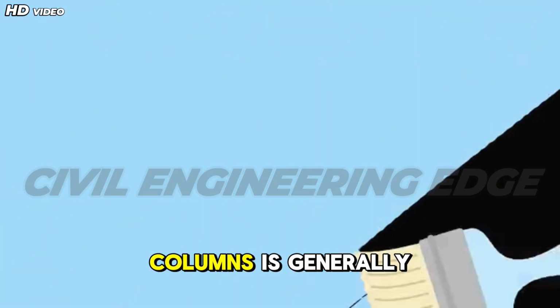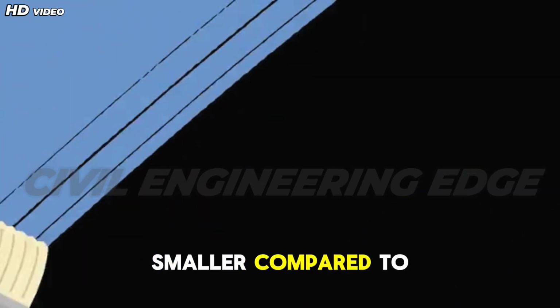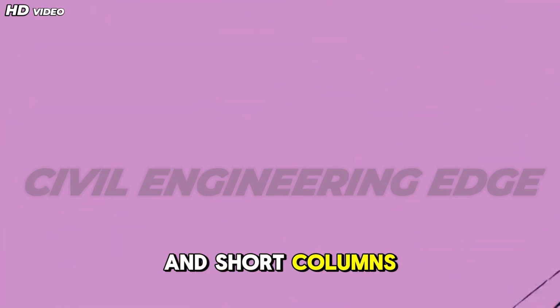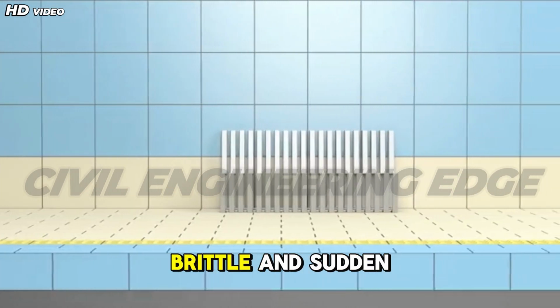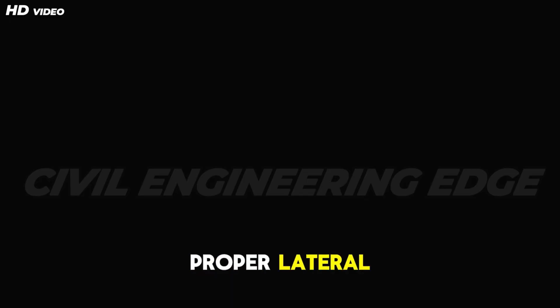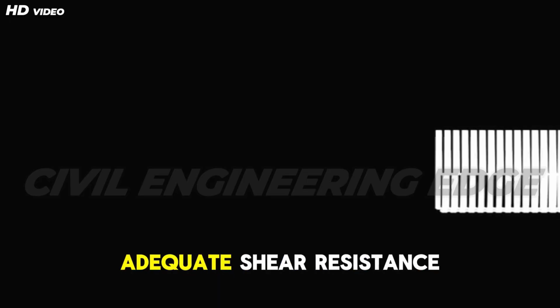Shear force in columns is generally smaller compared to beams, but becomes significant in seismic regions and short columns. Shear failure is brittle and sudden, making it highly undesirable. Proper lateral reinforcement ensures adequate shear resistance and confinement.